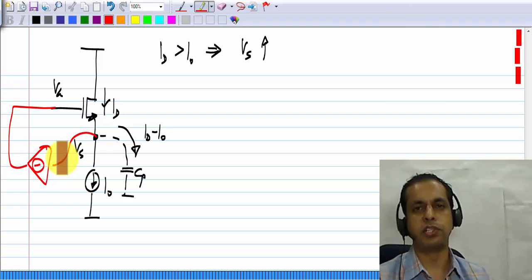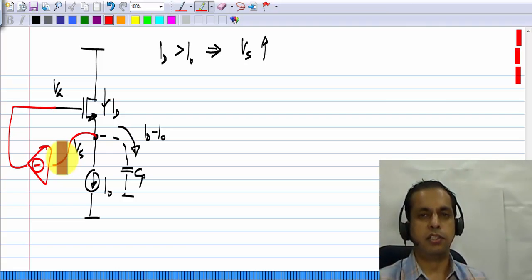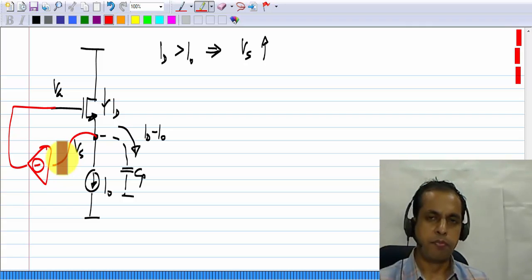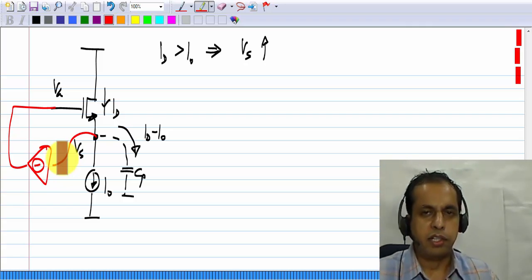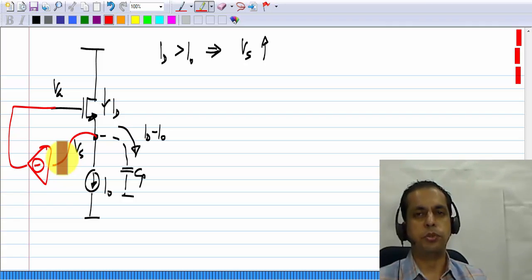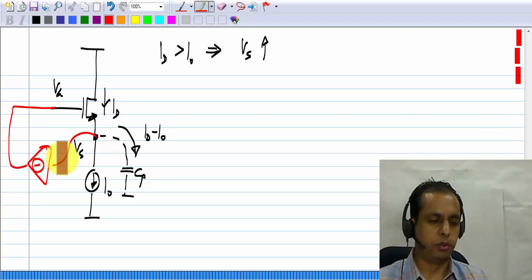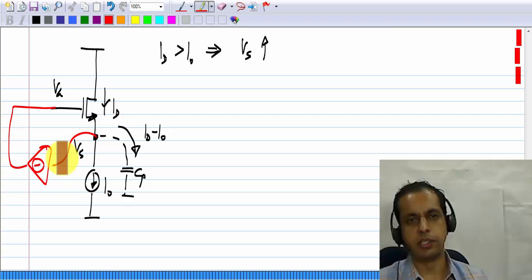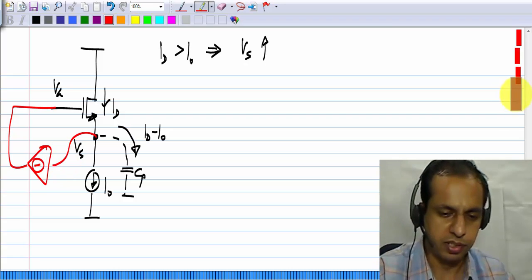So we have now discussed all four cases, sensing at either drain or source and feeding back to either gate or source. Again, this circuit is slightly more complicated than the first two types of feedback biasing that we discussed. So just for a common source amplifier, you would probably not use this, but there are many other circuits in which such an arrangement appears.